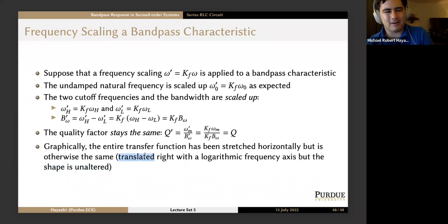If we ask you to plot the transfer function magnitude response and phase response, and then we say, now plot the magnitude response after you apply a frequency scaling of kf equals, I don't know, 9 times the square root of 51, you know that you just add log 10 of 9 square root of 51 to everything, but all the shapes will stay the same.